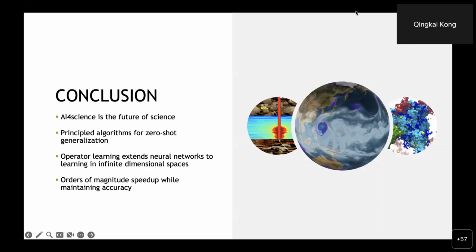Yeah, those are great points. So for the first, generally for non-periodic cases, the Fourier branch may not capture that very easily. You can correct that with Fourier continuation methods, and we also proposed that. But we also have an alternative branch, so we have skip connections, and that's a very efficient way to capture non-periodic conditions, and so we have architectures that handle that very efficiently. For the specific case of CCS, what we did was a nested FNO model. We have different FNO models for within the well versus outside. We have multiple levels, and they share the information across them.